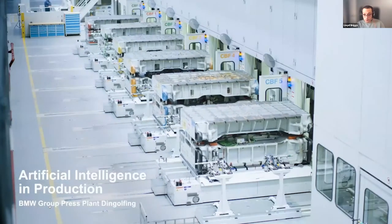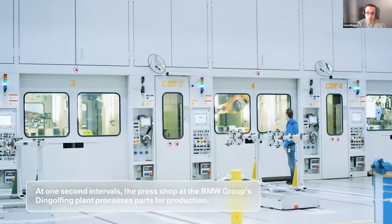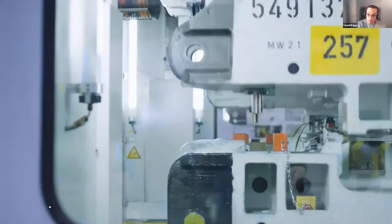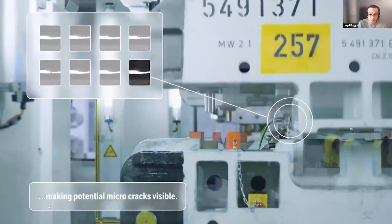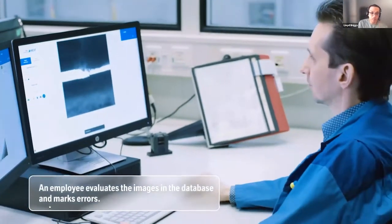In the press shop here, you can see that they're producing panels for the body for your BMW car. And what can happen in this process is you can easily get microfractures. And they're using infrared cameras here to detect microfractures at certain key points of the press panel. They're looking for a particular size of defect that's out of spec.